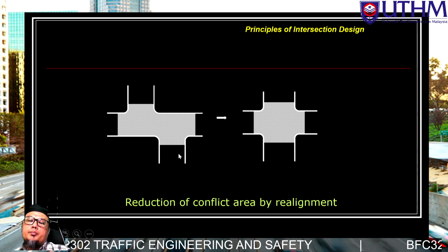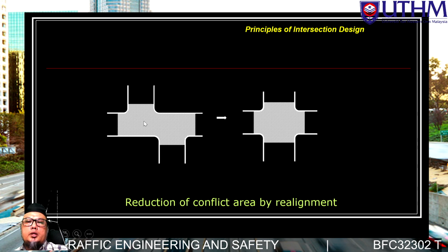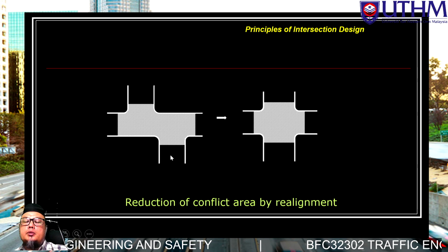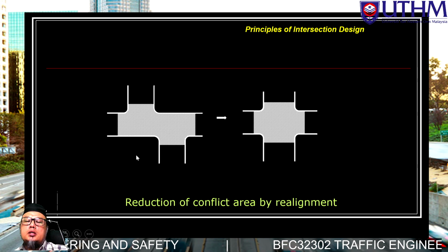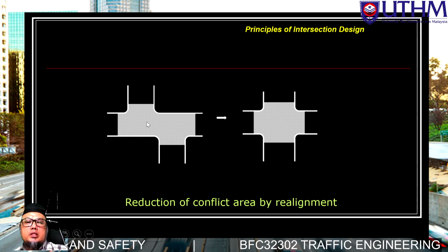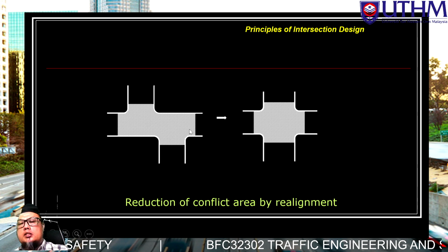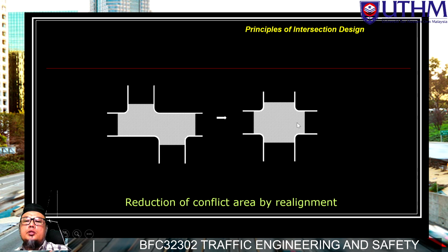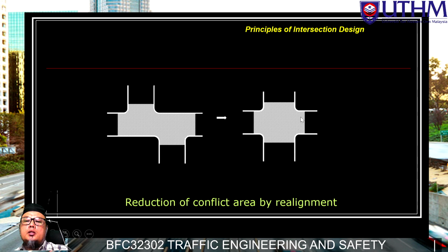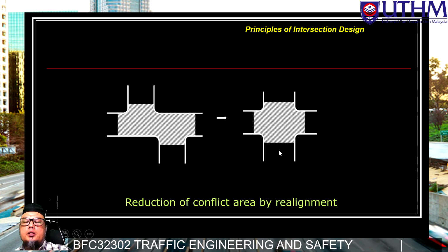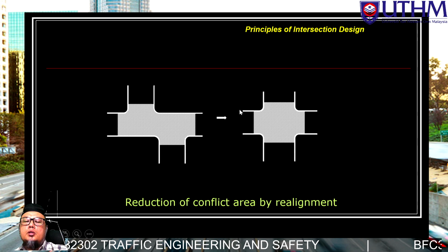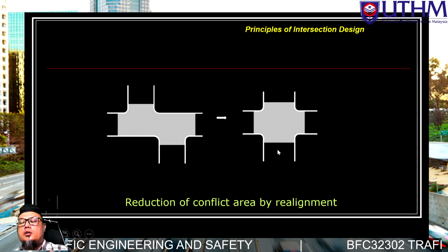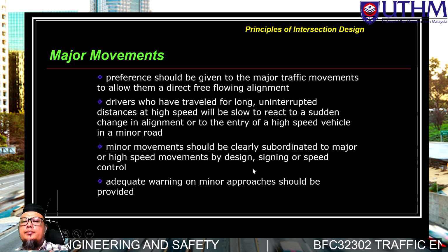If you notice at the Pitas Kuding junction, the access to Perwira and also the access to Taman Melewa in front of Masjid Pitas Kuding, the design is like this. It looks staggered but actually it is not a proper staggered layout. The layout becomes like this, so it is substandard. So we have to change to be this one. And make sure that when we design like this, it will lean more towards signalized interchanges or we have to provide channelized and pseudo flare to improve the conflict points.